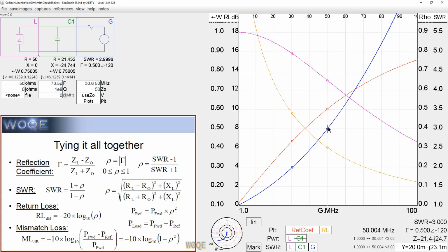We know that at 3 to 1 SWR, when the wave gets to the end of the load, what we reflect is half. So the reflection coefficient is basically 0.5. A 0.5 reflection coefficient coming back means that the power that you get back at the load is basically 1/4, assuming there's no loss in the circuit. So you would be down by a quarter of the power.